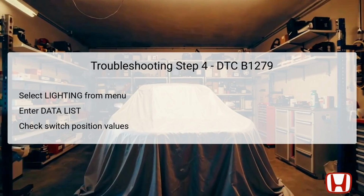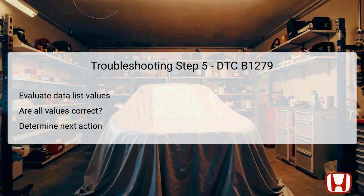Specifically, observe the data values associated with the passing switch and the high beam settings, as discrepancies may highlight issues within the dimmer switch circuit or its related components. This detailed analysis provides insight into how properly and accurately the components are transmitting signals, which can help determine the source of DTC B1279. Once the data values have been evaluated, it must be determined whether all the values are correct according to specified standards.